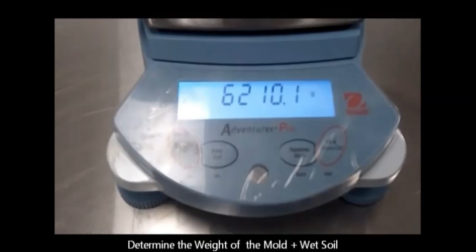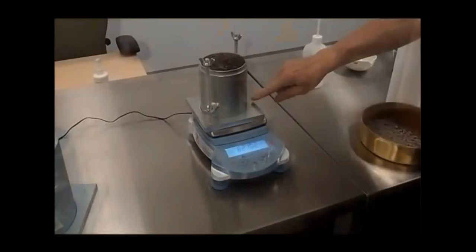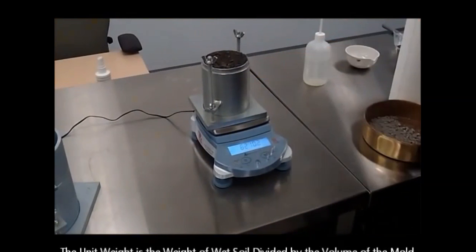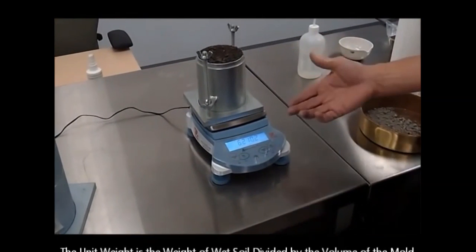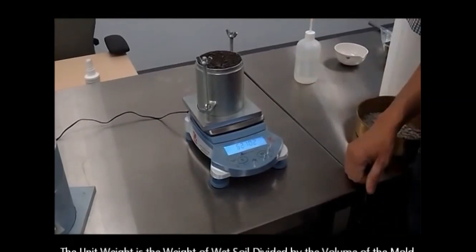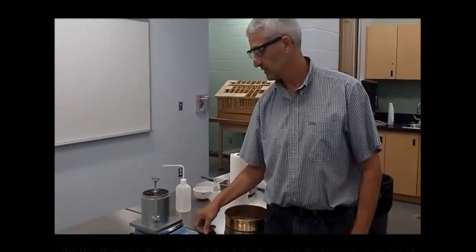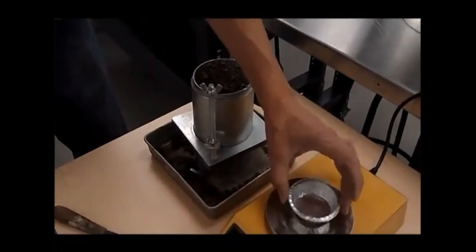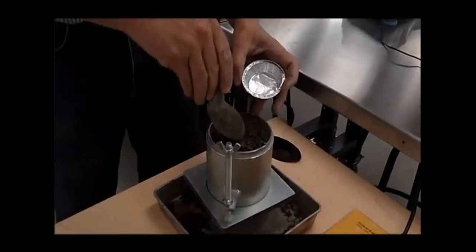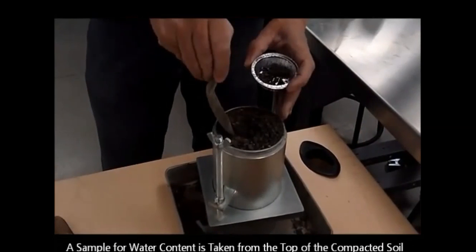So similarly, we'll do it for 4 to 5 trials, increasing the percentage of water. First we had added 4%, then we'll add 6%, 8%, 10%, 12%, and so on for the next trials. After each trial, we'll take some sample out of the compacted soil in the mold, and we'll keep that soil for water content determination.